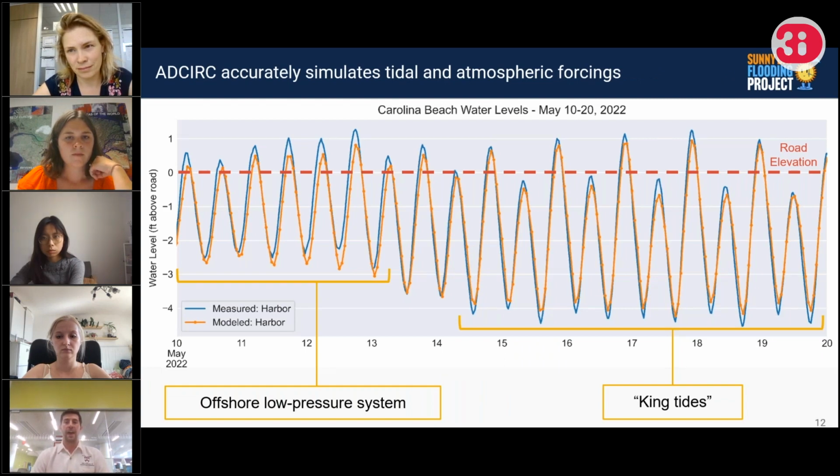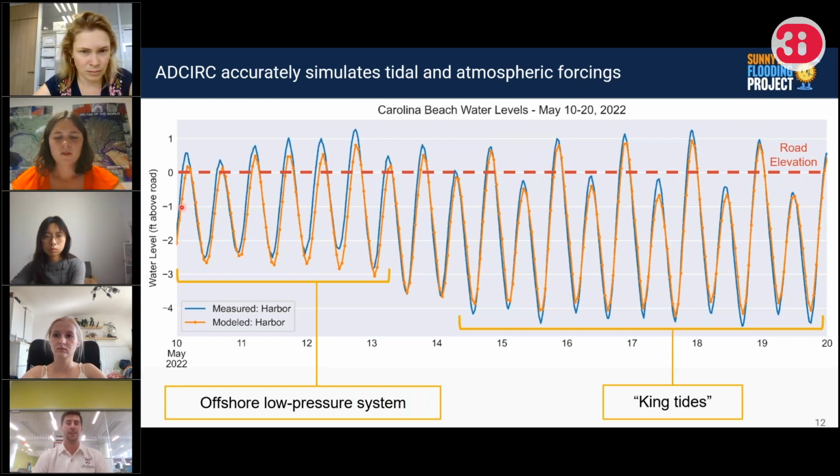I first developed the ADCIRC simulations, calibrating the model against a water level gauge in the Carolina Beach Harbor. This is a water level time series from May 2022. On the y-axis are water level in feet. Sorry about that for y'all who are familiar with meters, but basically 3 feet is about 1 meter.